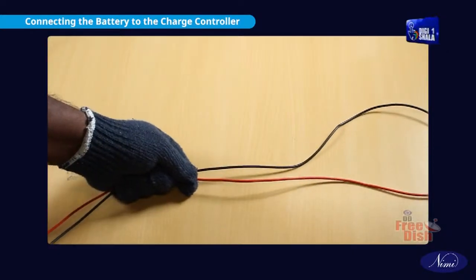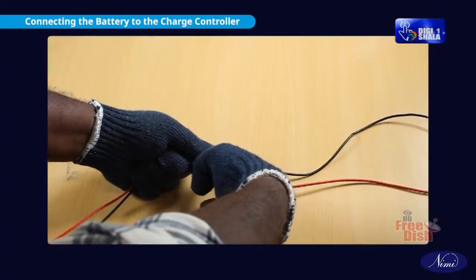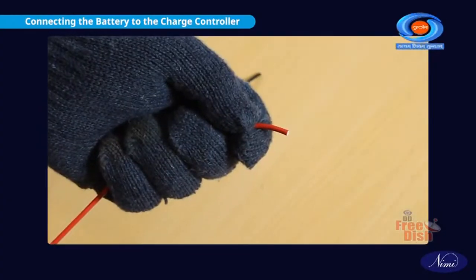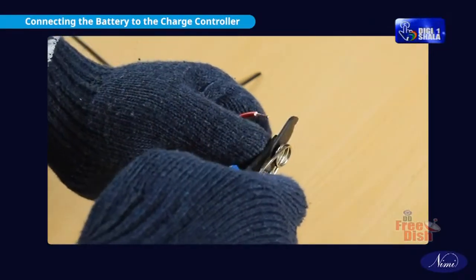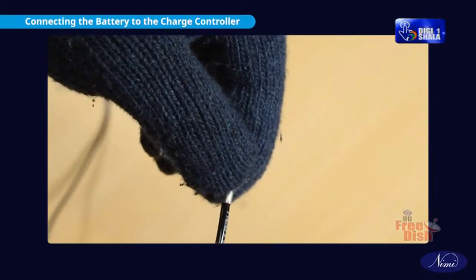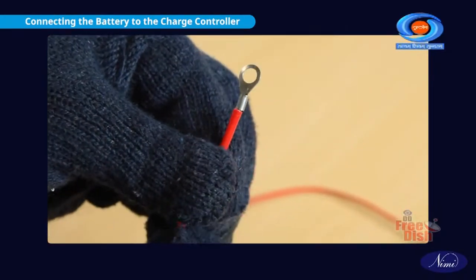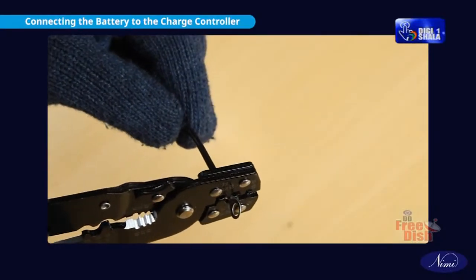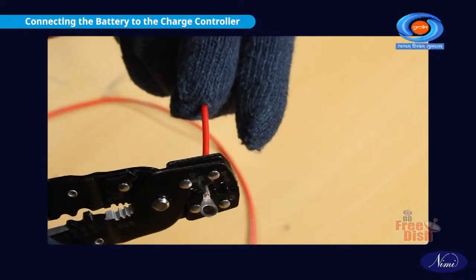Measure and cut 2 lengths of electrical wire required to connect the battery to the charge controller and the circuit breaker. Remove the insulation sleeve at both ends for 12 mm and insert the conductor into cable lug terminals as shown. Use the crimping tool with the correct slot. Crimp the lugs on one end only of both wires.